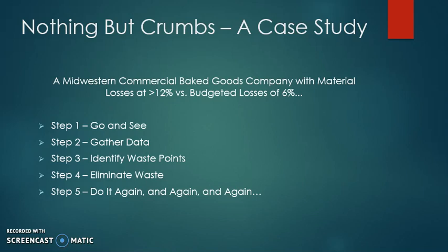To eliminate the waste, the management team brought awareness to the issue and told the line workers what the impact was to the organization's bottom line. They also implemented a process that required measurement recording during batching and spill cleanup so that they could properly track raw materials through the entire production process. Then they repeated the process, and the second time around, they ended up automating the capture of the weight data at batching. This decreased the losses even more, and now the management team is planning the next event soon so they can eliminate even more waste.